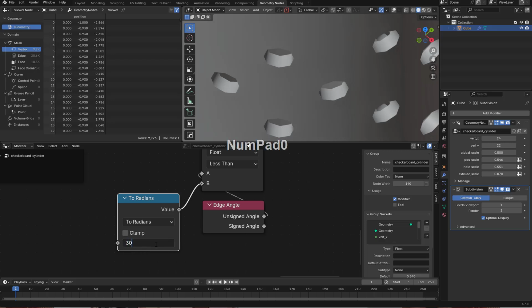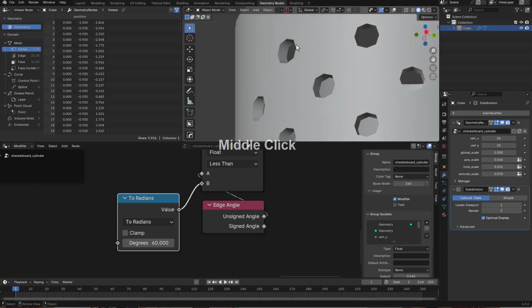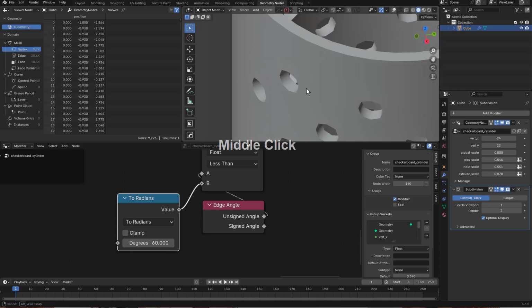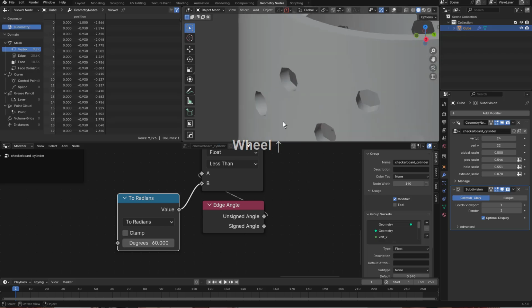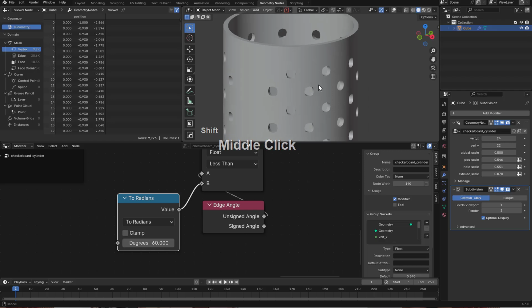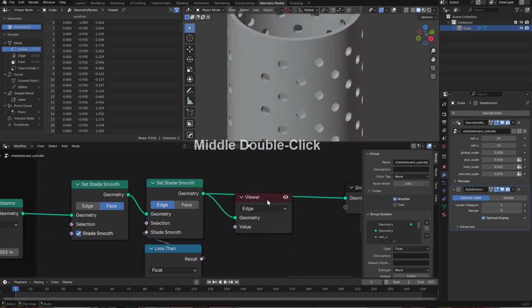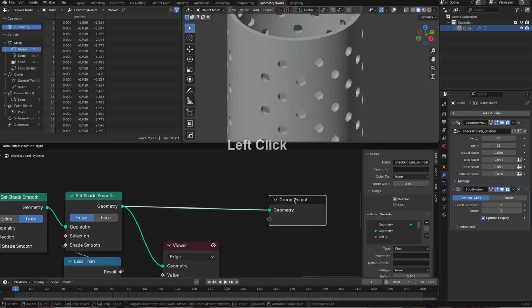And now we can put in something like 30, maybe raise it up to, I don't know, 45. We'll raise it to 60 just to ensure that we have only these edges being marked sharp, and along the top edges anything lower we see it begins to clip those because we would need basically more smoothing in our subdivision to grab it. But continuing on, the next thing also is that we want it to hold for the subdivision well. So let's take a look at that.